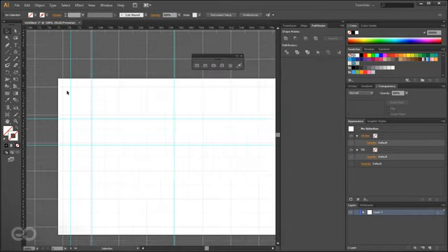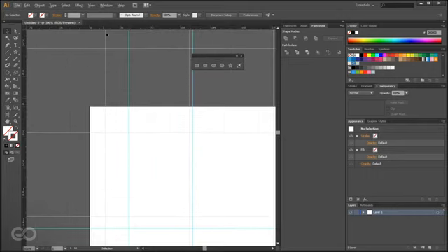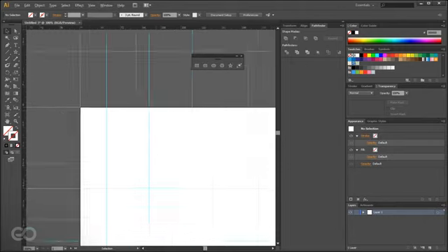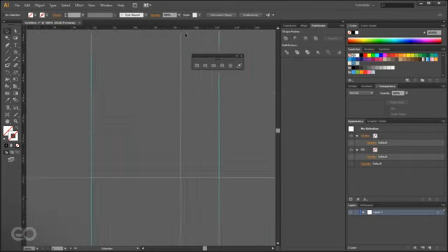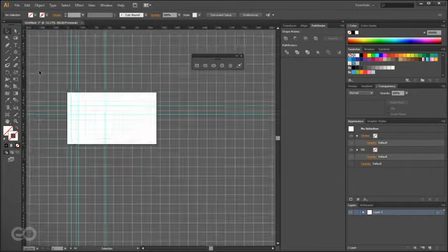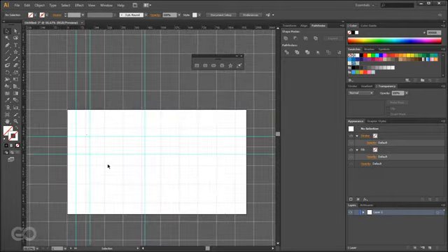So you can see this is 100 pixel grid lines. If I zoom in, you can see this grid line position is somewhere at around 18, and this is at around 118. So I exactly want it to start from 0. So for that, I'm going to go ahead and change this here to snap there, and also I'm going to change my global rulers to start from here. So as you can see, as soon as I change my global rulers, it is exactly set, and my grid is also going exactly. So that is done. It's going exactly at 100, but because of my 72 ppi I'm not able to see that.